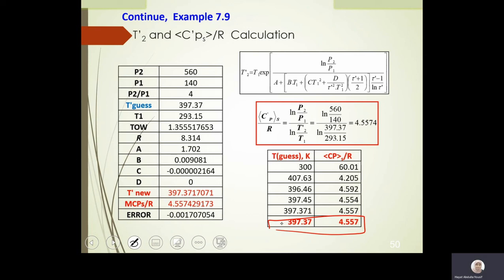So, conclusion: with the pump, you do need three types of equations. One equation relates efficiency, or delta H, with delta HS, which is called the efficiency equation. The second one is how to get W isentropic, which is delta HS here. The third equation is how to relate delta H and delta S for a liquid. If you know those three equations, then you can solve any problem.